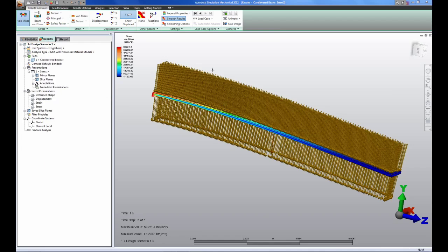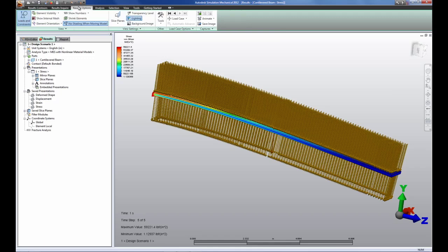The gold arrows represent the pressure loading acting on the top surface. As specified, we can see that these arrows are perpendicular to the surface. We can turn these arrows off so that we can better see the graphics information. Select Results Options, and then Loads and Constraints.